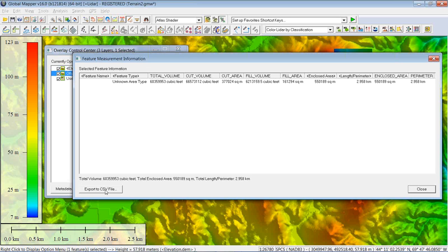Up until I believe it was version 15, the determination of where to calculate the volume from was derived from the z-value of every vertex. In other words, Josie created an area with maybe a dozen or so vertices. Those elevations were used to create a temporary terrain surface from which to calculate. Similar in process to what Josie had done previously, which was calculate the volume between 2 surfaces. Obviously, in this case, Josie just drew an area, so the surface didn't exist. So it derived the elevation and ultimately generated a grid from the vertices.